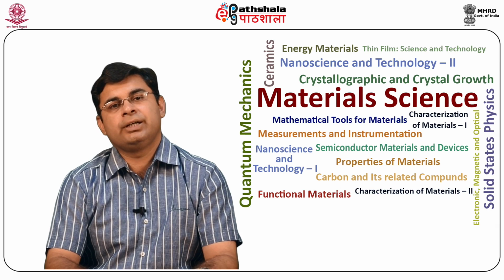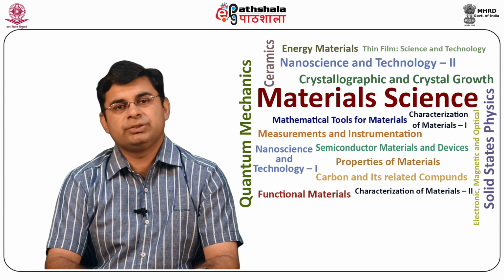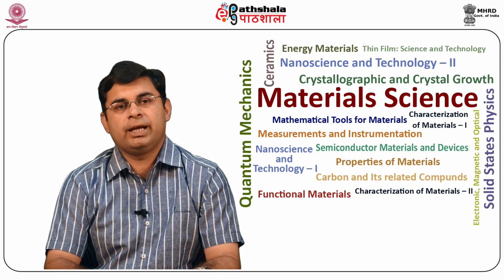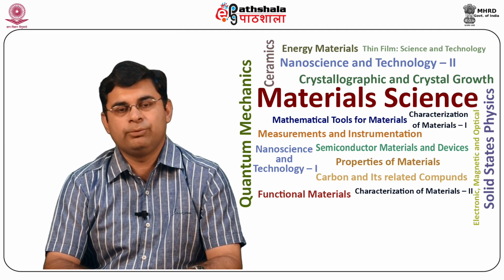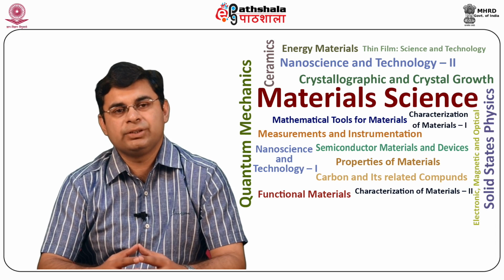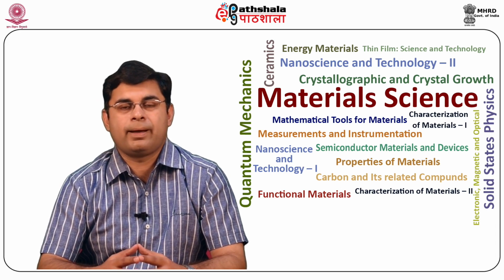Now, there are two types of bridge circuits. DC bridges use DC voltage and are used for measuring resistances, whereas AC bridges are used over alternating voltage and for measuring impedances of circuits consisting of a capacitor and an inductor.